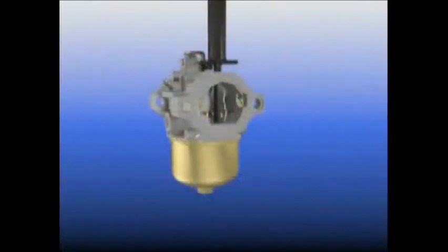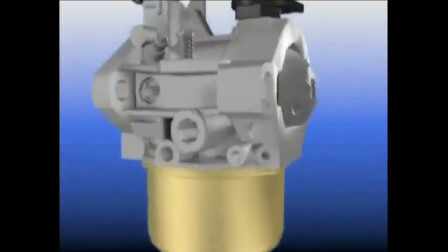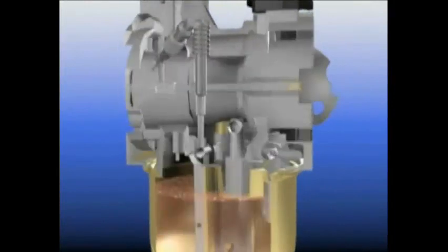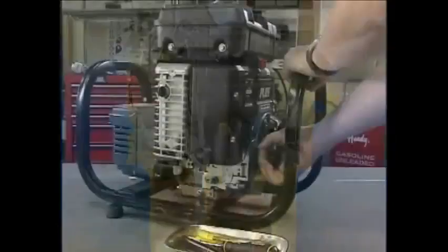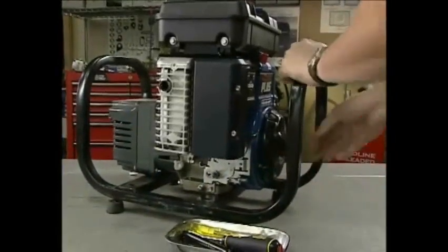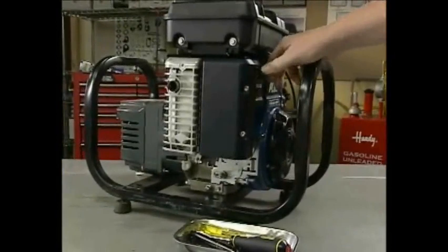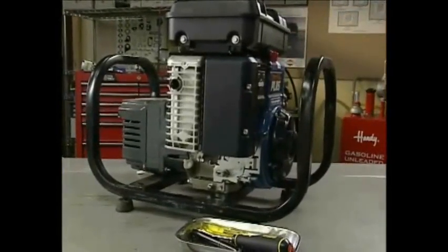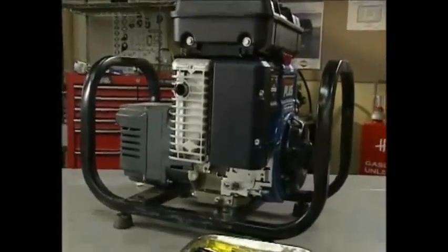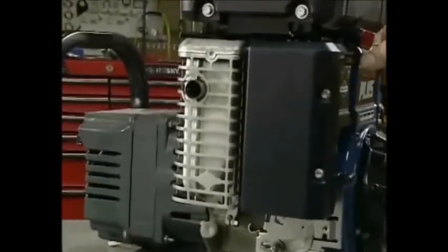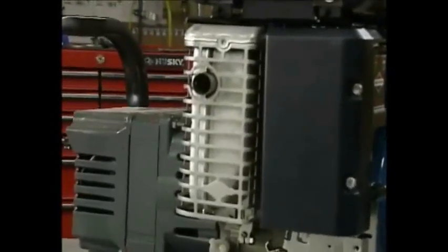Dirt and debris entering through a ripped or torn air cleaner can collect in the idle air circuit, causing it to become clogged before the pilot jet. When this occurs, the pilot jet will only flow raw fuel to the combustion chamber at idle, resulting in light black smoke exiting the exhaust. The carburetor will mildly hunt and surge due to this symptom.